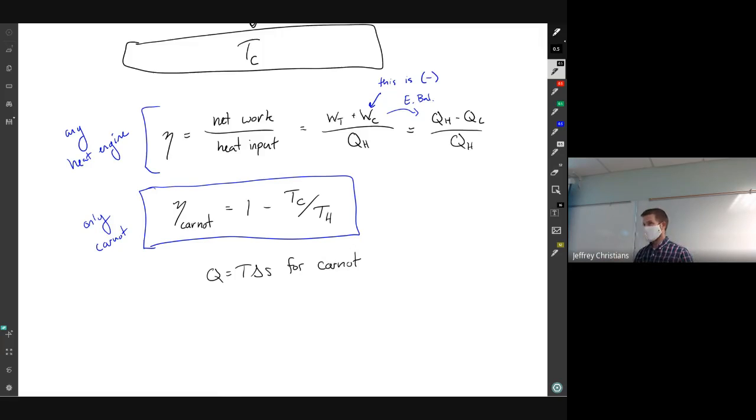That will be a better place because it has a lower cold temperature. If you could make two power plants, one has a higher hot temperature, that one, all things being equal, will be better. So it gives you kind of a direct way that temperature plays in. This applies anytime we're trying to take thermal energy and convert it to work. So it actually applies even in systems where it's maybe not obvious.